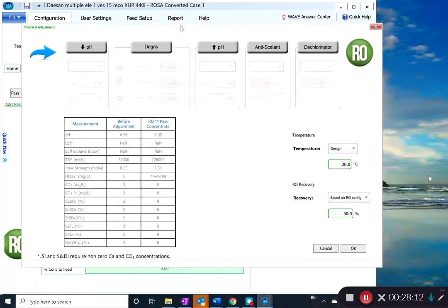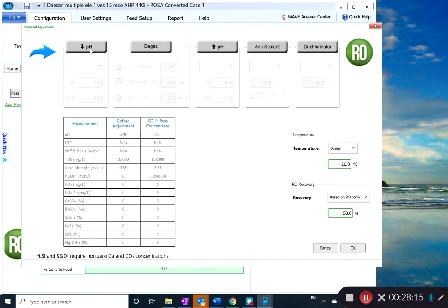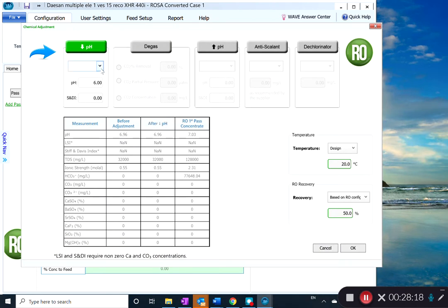And if you see this part, you will have different option. Let's say pH. Okay, we have initial pH 8, but we need to decrease the pH to 6 because to avoid inorganic scaling in the pump and RO, also some stiff inorganic scaling parameters, also degas. So this one does not require in the seawater desalination plant. This require for groundwater.